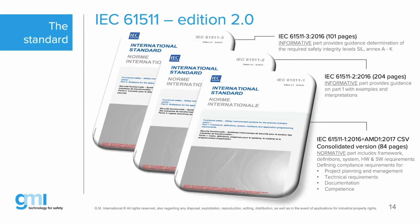That means if you look at the standard, here you have a copy of the 3 parts of the standard, edition 2. If you look here on the bottom right corner, we show IEC 61511 part number 1. So when you see -1, that means part number 1, the first part of the standard. That's exactly 84 pages in English. And those 84 pages are the normative section of the standard. And that's important to understand. Normative means if you have to comply, then you have to show evidence that you comply with the normative section, which is different for part 2 and part 3, because those are the informative sections.